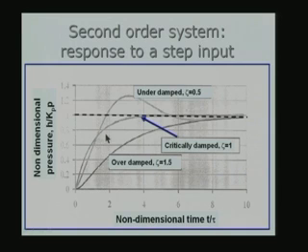So, what happens in the underdamped case? Here I have taken zeta equal to 0.5, and zeta less than 1 corresponds to the underdamped case. You see that the pressure goes up and the height overshoots to a little more than 1.2, about 25% more. Then it slowly comes down, goes below, and again after 10 time constants it is just about to settle down to the steady state value.